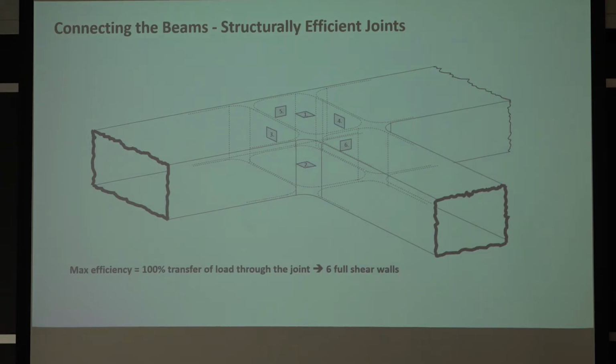One thing I want to talk about first here is joint efficiency. We talked about this a little bit with the lugs on the bicycles. If you have one load path this way, and you have another load path this way, and you're pushing or pulling on this tube, but this is a very thin wall, you're not going to transfer that load very efficiently. Very important point. You can have the best load paths in the world, you can have the best thicknesses chosen for every panel, but if you don't have efficient lugs, efficient joints, then you're in trouble because you'll lose a lot of that stiffness in the joint.